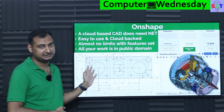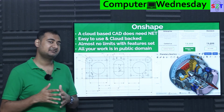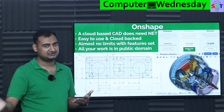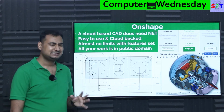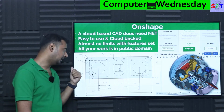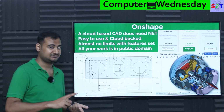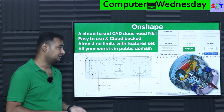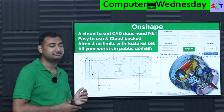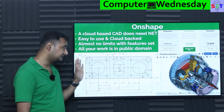And this is the same part I created, because as I specified, Fusion 360 does not allow DXF export directly. You have to unfold the sheet metal and then directly transport that to DXF output. DXF output is a big issue. So I jumped into Onshape. Now you have to understand, I have jumped between many software. Like, I have used Max, I have used Maya, I have used Fusion 360, I have used Onshape. And how hard it is to jump into a software defines how well thought out it is. This software I picked up in minutes. Like, fundamentally, it's surprisingly easy.